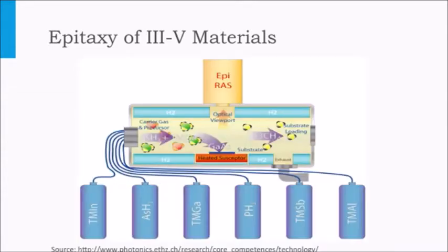In general, metal organic chemical vapor deposition, abbreviated as MOCVD, is used to deposit the III-V semiconductor layers. Typical precursor gases are trimethyl gallium, trimethyl indium, trimethyl aluminum, arsine gas and phosphine gas. Surface reactions of the metal organic compounds and hydrides containing the required metal chemical elements create the conditions for the epitaxial crystalline growth.